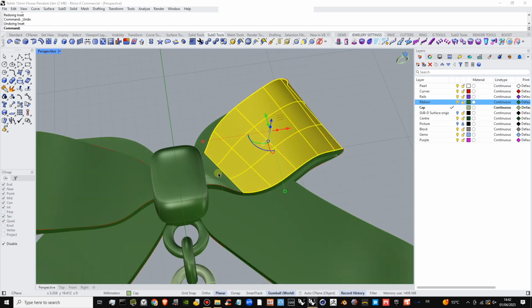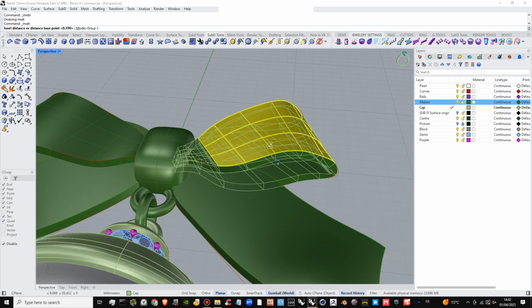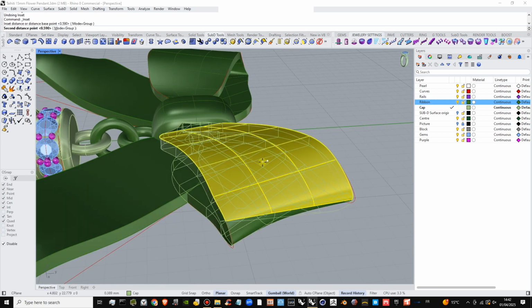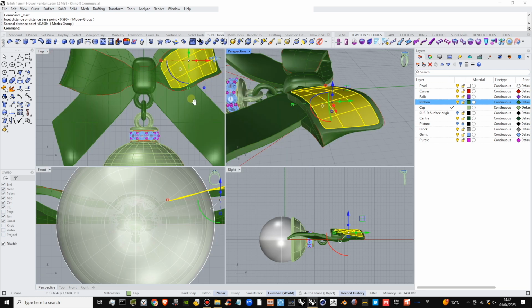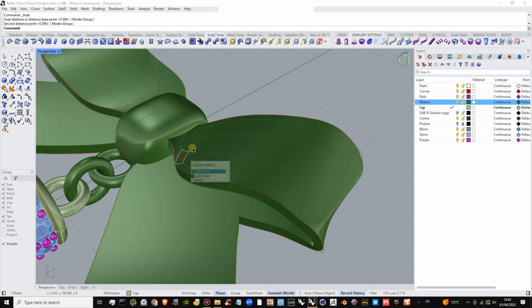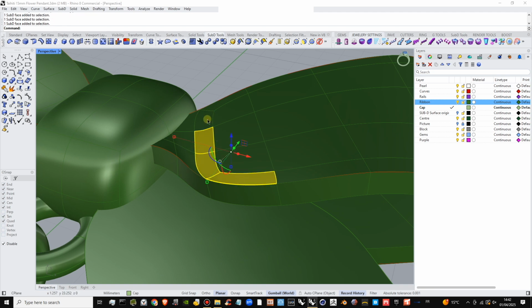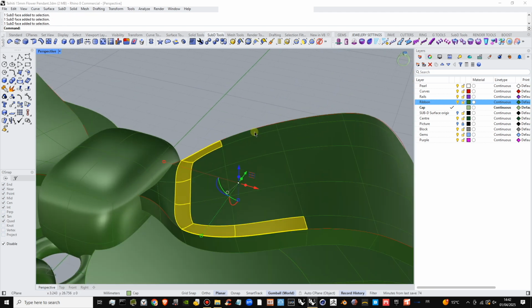I decided to deselect the one on the corner here, and we are going to insert that, and that's around about, that's a bit much, that's about 1/2 millimeter. And what we're going to do is select the outside lying surfaces of that particular selection. So you don't want the edges, you want the surfaces.